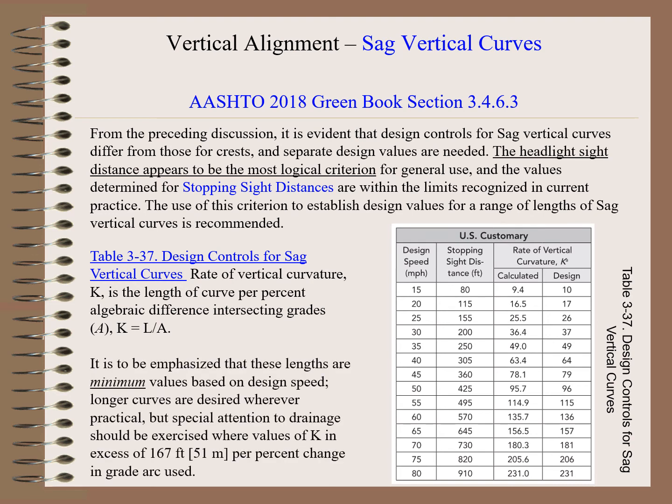It is to be emphasized that these lengths are minimum values based on a design speed. Longer curves are desired whenever practical, but special attention to drainage should be exercised where values of K in excess of 167 feet per percent change in grade are used.